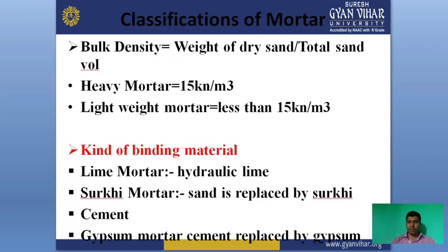In the pounding method, lime and sand are mixed in a dry state, and the mixture is placed into pits, and then water is added to the mixture by repeatedly pouring up and down. It means the required amount of water is added at equal intervals. When the mortar mass becomes continuous, it is taken out of the pits to be used in masonry work.